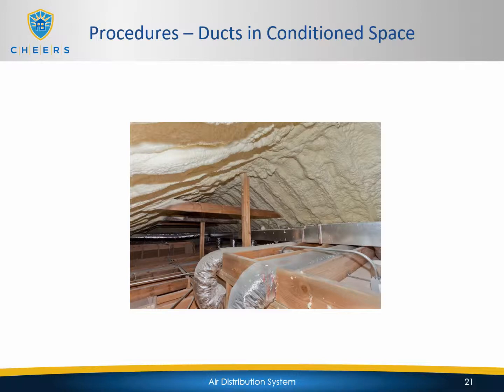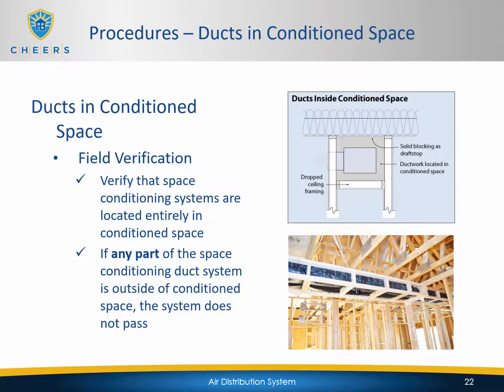So now we'll be talking about ducts in conditioned space. For ducts in conditioned space, for field verification, the HERS rater has to verify the space conditioning systems are located entirely in the conditioned space. This is including the furnace and the coil. If any part of the space conditioning duct system is outside of conditioned space, the system does not pass.